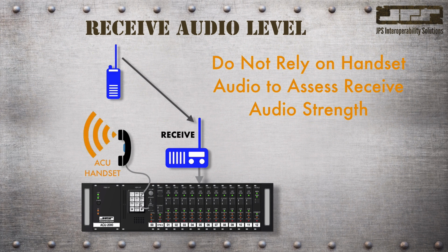And do not be fooled by the audio being emitted by the ACU handset or the integral speaker. The audio might sound fine, but might actually be too weak or too strong once delivered to the ACU backplane. This will create an under or over modulated condition with the disparate radio and telephony systems associated with the ACU Gateway. Always rely on the signal LED and not the ACU speaker to assess the receive audio levels.